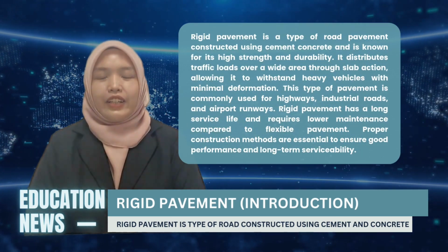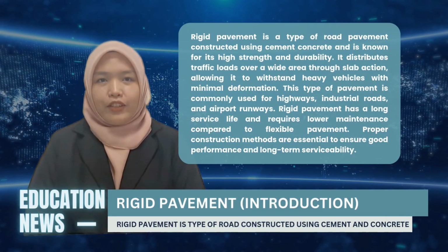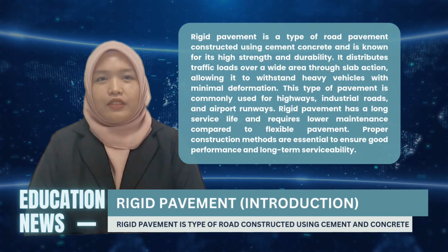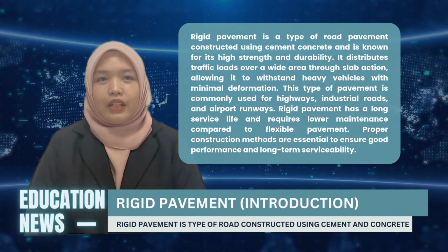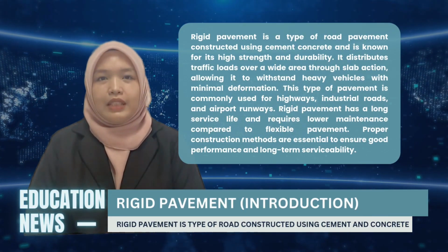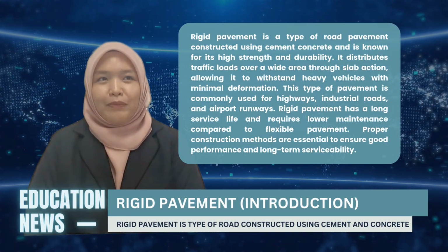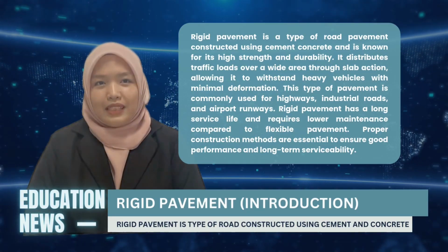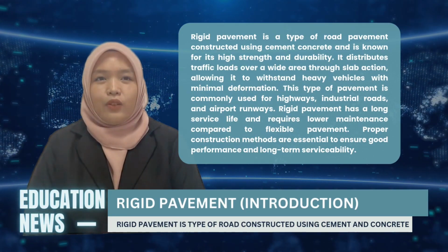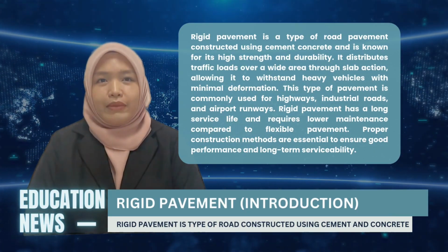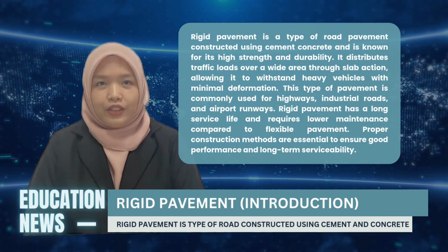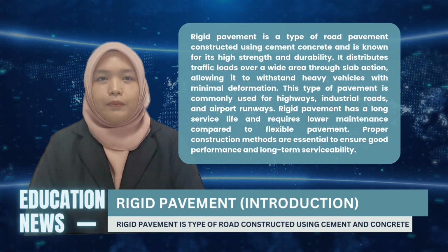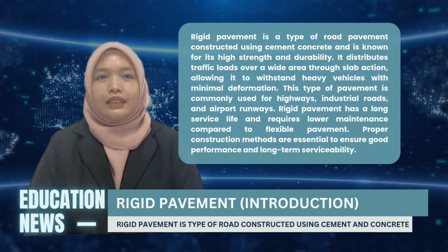Rigid pavement is a type of road pavement constructed using cement concrete and is well known for its high durability and strength. It distributes traffic loads over a wide area through slab action, allowing it to withstand heavy vehicles with minimal deformation. This type of pavement is commonly used for highways, industrial roads, and airport runways. With its long service life and lower maintenance requirements, rigid pavement remains a reliable choice for modern road construction. However, proper construction methods are essential to ensure good performance and long-term survivability.